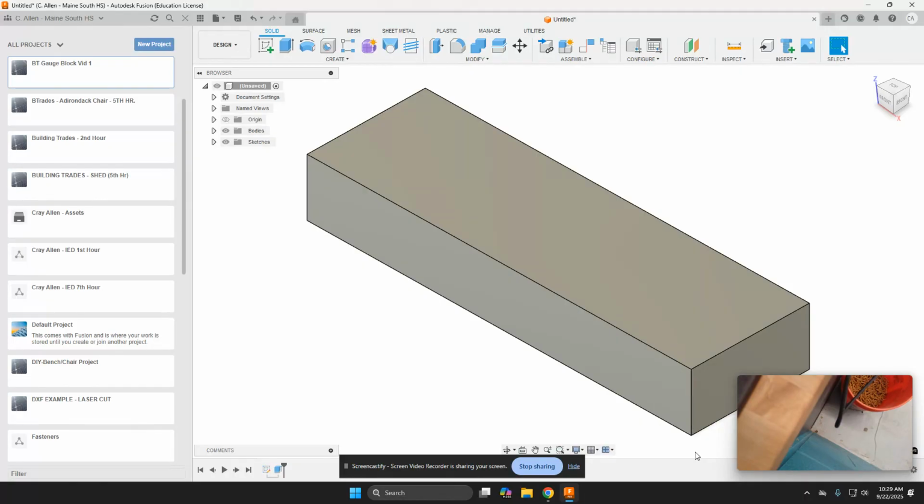Now, we talked about adding drywall, which is usually 1/2 inch, to the inside of walls. When you start adding other materials, your wood is actually a little bit smaller than 4 inches, because interior walls are typically 4 inches standard in width inside a house. So in order to get to that 4 inches with 1/2 inch drywall, how deep do you think this piece of wood would be? Would it be 4? It's actually going to be 3.5.